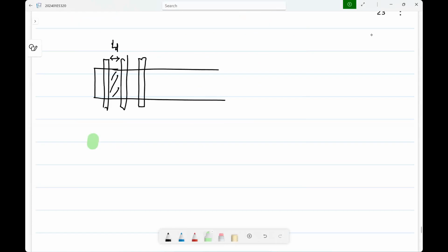Whereas in the other case, basically you have this, maybe I'll show it in the same direction. I have this on each side. So if you calculate it, you will see that basically because of that, the drain area being shared by 2 adjacent fingers, it will become approximately half. Okay.